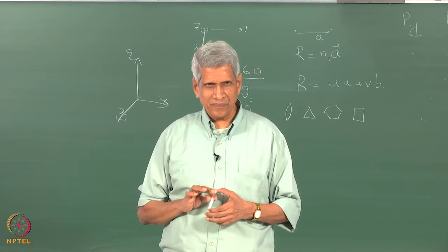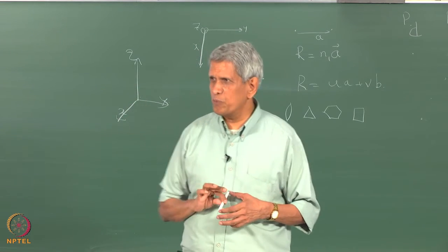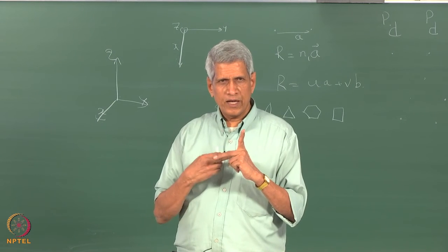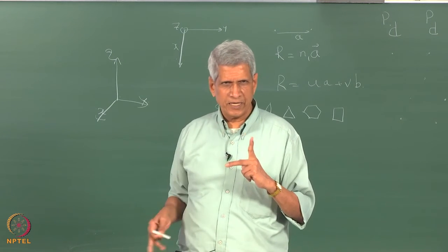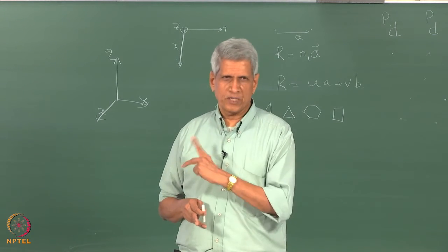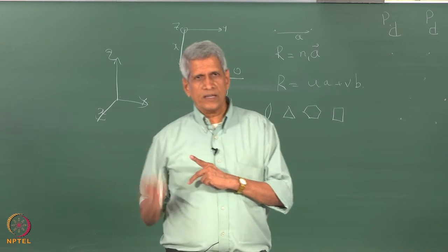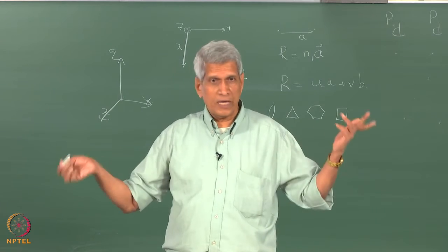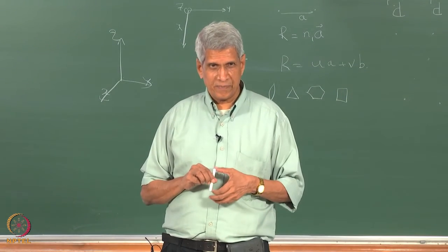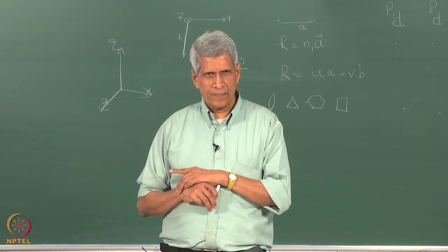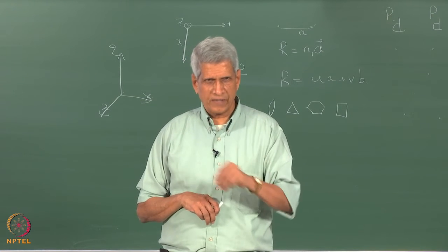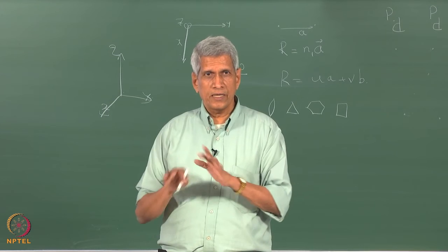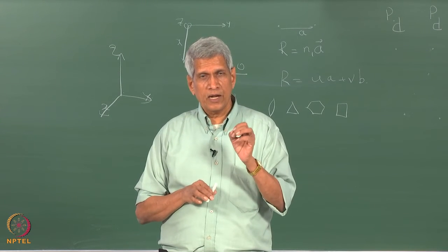It can have more than that also, but the minimum is, if it is there, then we say that this is monoclinic. If along 3 directions which are perpendicular to each other, there are two-fold rotation axes, only two-fold rotational symmetry, then it is going to be essentially an orthorhombic structure, right? If a crystal has got only one 4-fold rotation and there could be anything else other than that, then that is the tetragonal structure. Suppose a crystal has got only a 6-fold rotation, then it becomes hexagonal. Suppose a crystal has got only one 3-fold axis rotation, then it becomes a trigonal or rhombohedral.